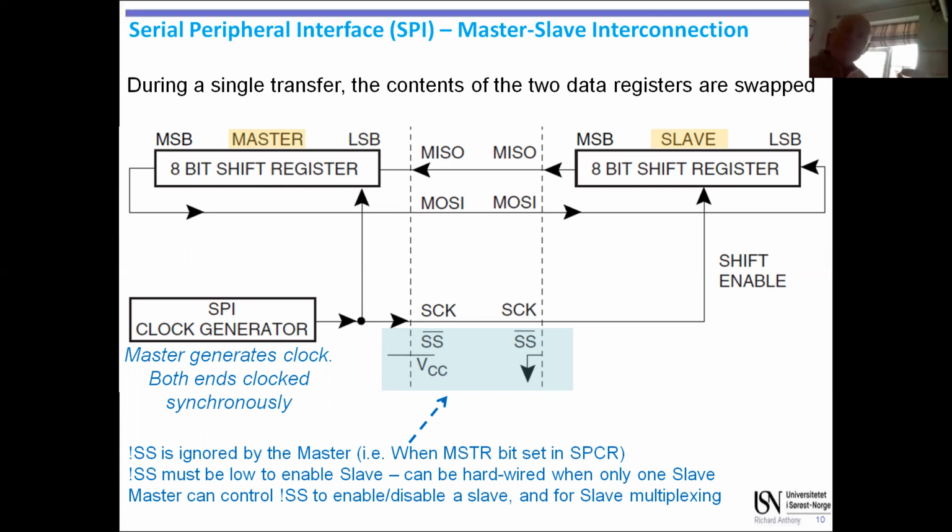One end may be generating data and putting it in that register, but it doesn't control sending it. It doesn't matter as long as the master side is causing this process to happen at a suitable speed. If the slave is reading the temperature and putting it here once per second, and the master is reading this once per second, or even at a slightly different speed, it will still always get the latest value that is in the register.